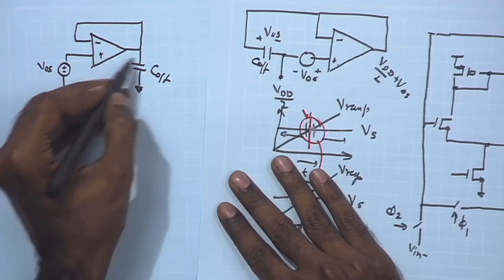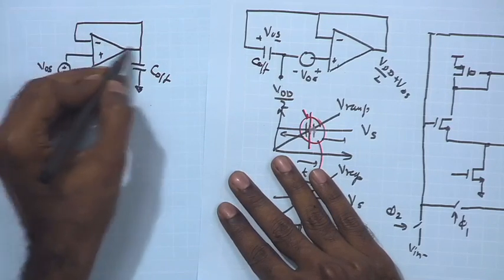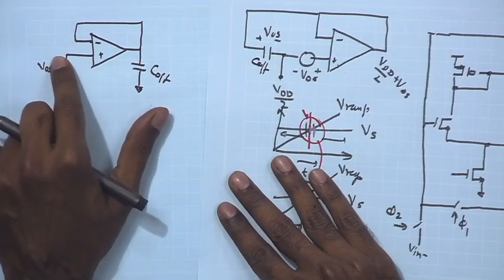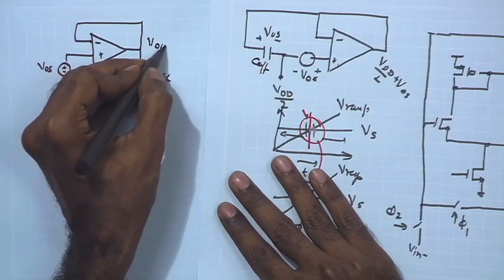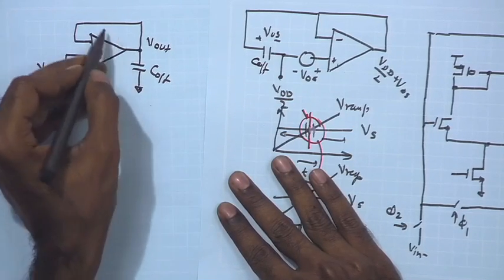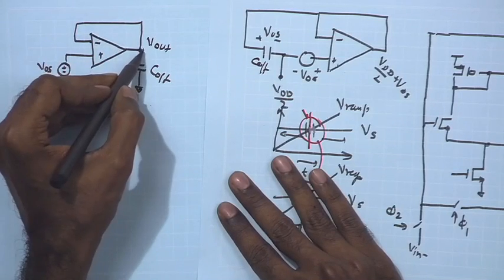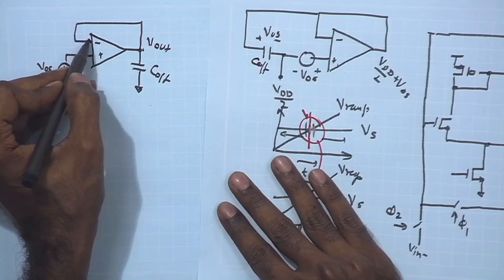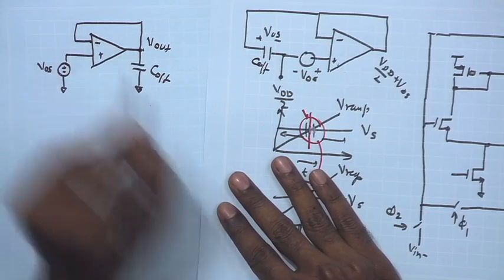Now, in this case, once again we have the output voltage being fed back to the input terminal in series. Therefore, at the input we have series configuration, the output voltage V out is being sampled and fed back to the input. So, at the output we have shunt, and the feedback factor is unity, because we are just sampling the V out, and the feedback signal to the negative terminal of the op amp is just the V out as it is.